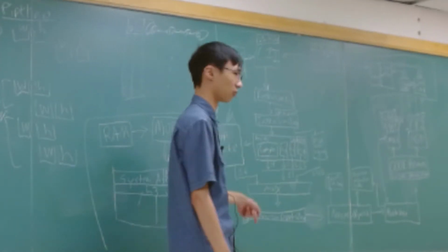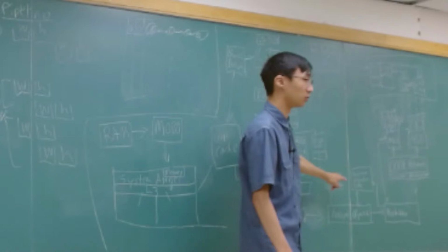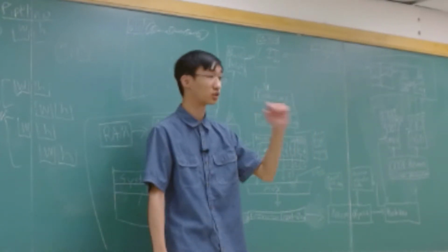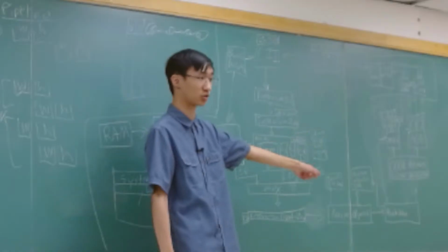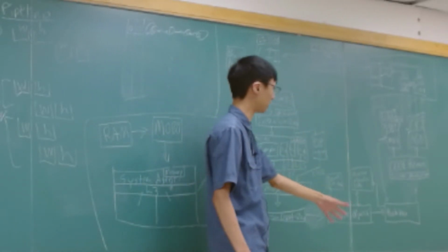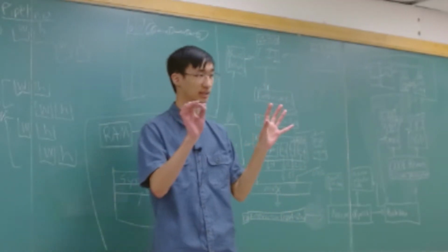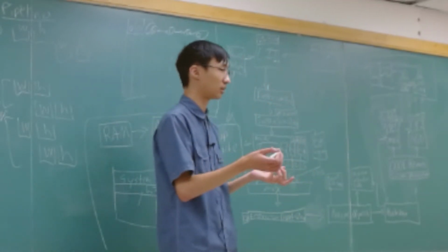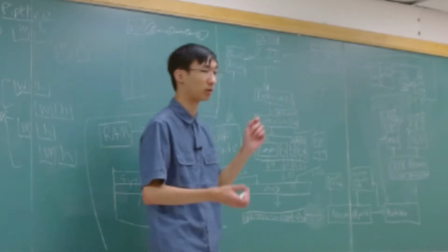So if you get it wrong, what happens is this branch order buffer that I was talking about earlier will keep that snapshot so that we can roll back this state, the microarchitectural register state, and flush any instructions that we don't need, and remove any registers that are storing things that we don't actually want, that are incorrect data, right?